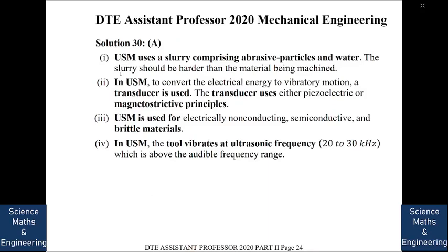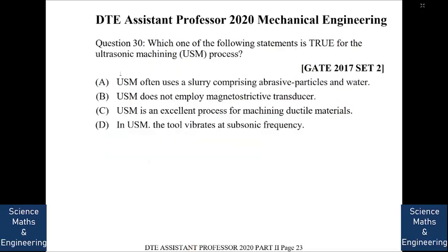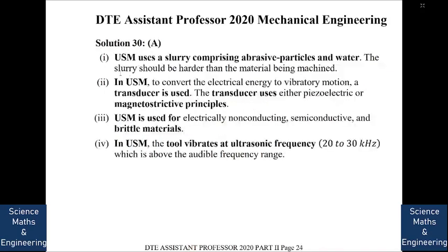Next, in ultrasonic machining, we use electrical energy and convert it to vibratory motion, and for this a transducer is used. Now this transducer uses piezoelectric or magnetostrictive principle. So option B, that is USM does not employ magnetostrictive transducer, is false.